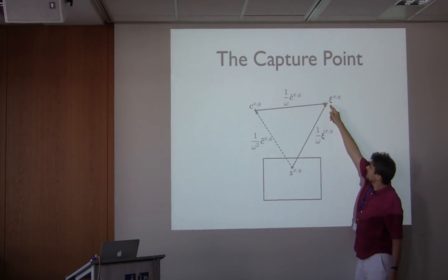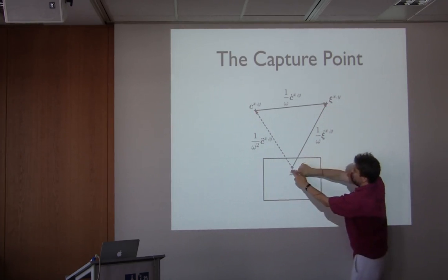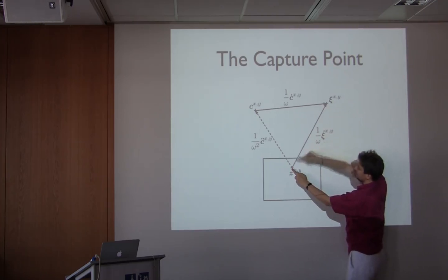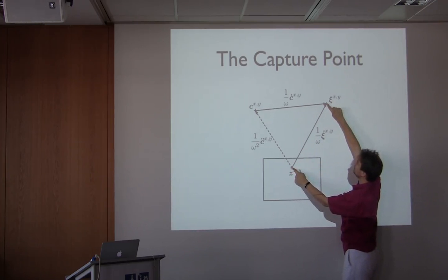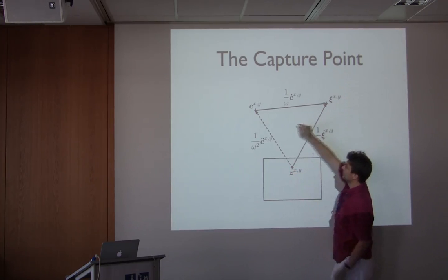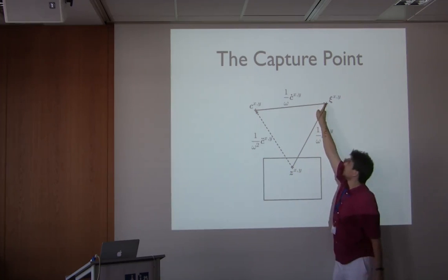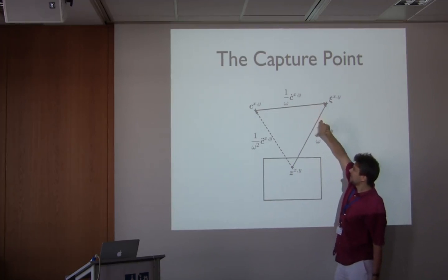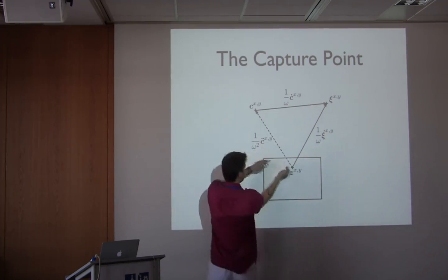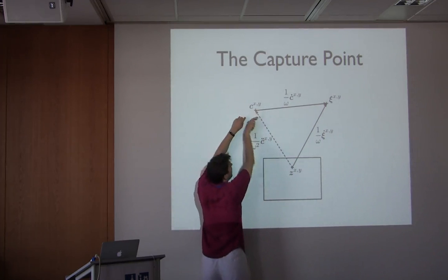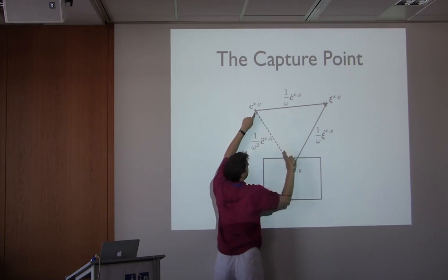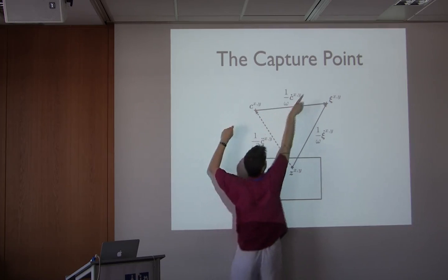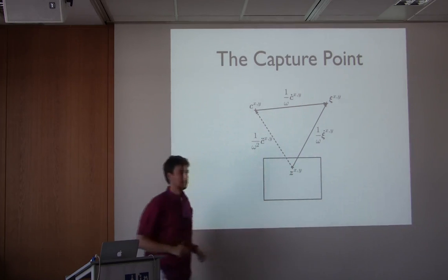So the capture point will go away, so the speed will be in this direction with respect to the center of pressure. But the center of mass is going towards the capture point. And the combination of those two first order dynamics gives you an acceleration of the center of mass which goes in this direction. So it goes with this speed, but with this acceleration. So it will go like that. Is it clear?